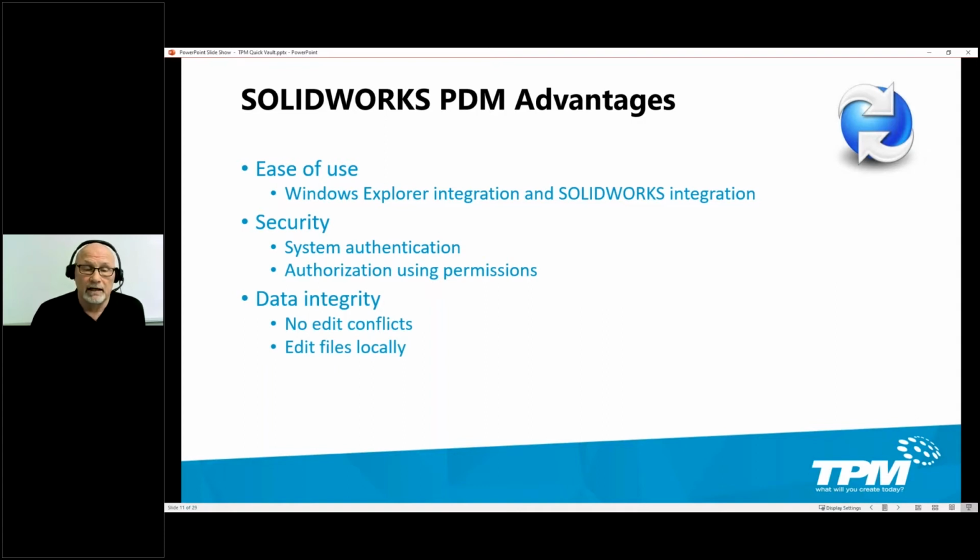Data integrity. There are no edit conflicts because in order to edit a file in PDM, you have to check it out. When you check out a file, it more or less locks it to that user. That user is the only one that can make changes to that file, even if someone else has permissions to do that. Once they check the file back in, then another user with permissions can check it out and make modifications to it. So you don't have a situation where two people are trying to edit the same file and you end up with an edit conflict.